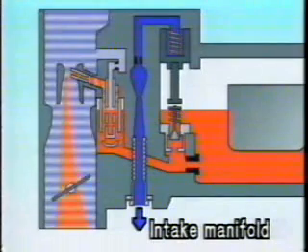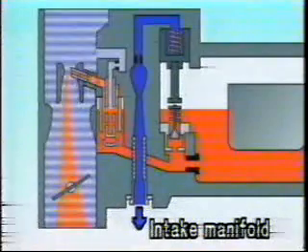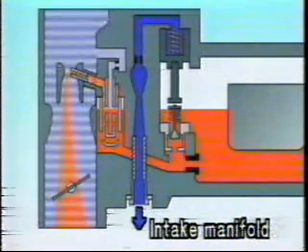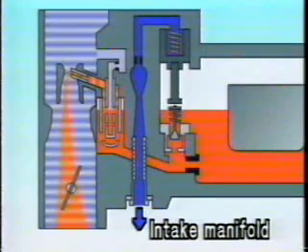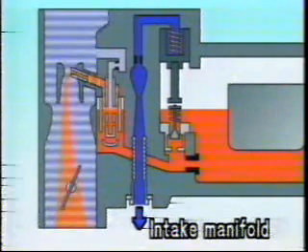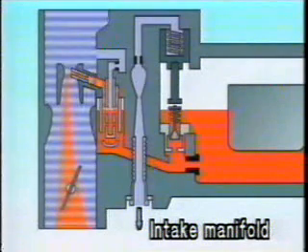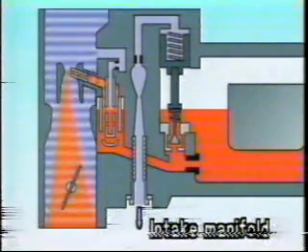When driving at a constant speed with the opening of the throttle valve small, the power valve is closed due to the high manifold pressure. When a big increase in power is needed, the driver depresses the accelerator pedal, thus opening the throttle valve wide. This causes a decrease in the manifold pressure. When the pressure in the manifold falls below the standard value, the spring pushes down the power piston and opens the power valve. The flow of fuel becomes less restricted and the fuel is delivered from the main nozzle.